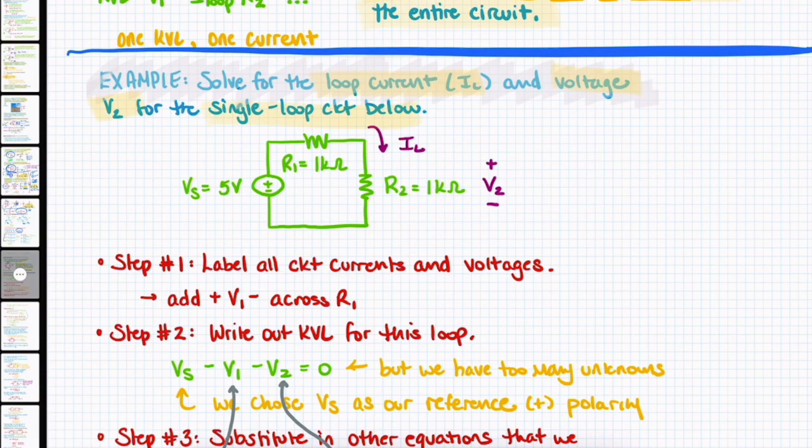All right, so let's take a look at what we have. We have an independent voltage source. Again, it's a circle or an oval, so we know that it's independent. And it has the plus and minus on the interior, so we know it's voltage. Then we have a resistor and a second resistor. This is actually a very specific type of circuit called a voltage divider.